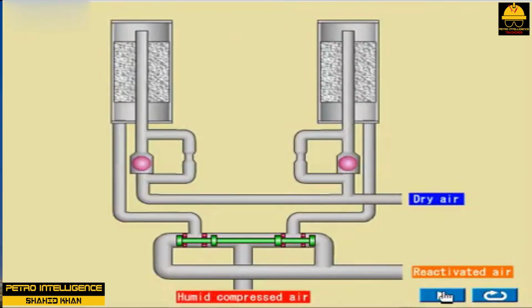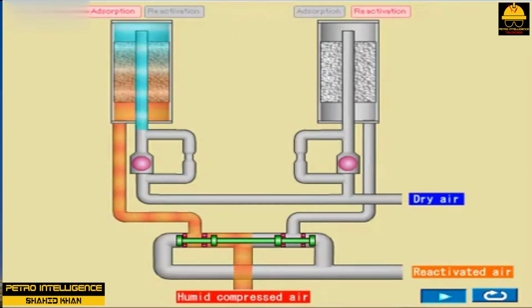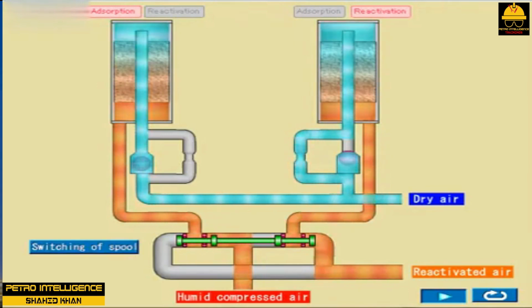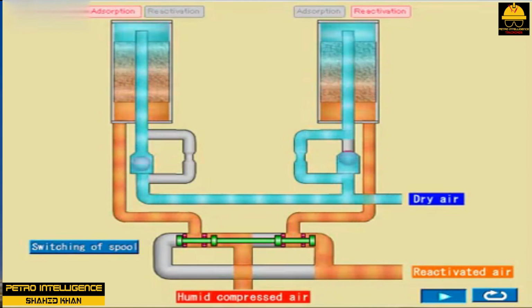A regenerating gas dryer usually consists of two vessels, beds, containing a granular solid. The solid is specifically chosen for its high adsorbency of the target vapor and ease of regeneration. Piping and valves connect these beds such that the gas being dried enters only one bed. The solids in the other bed are separated from the process so that they can be regenerated. When the first bed becomes saturated, it is switched off the line, the second, regenerated bed is put on the line, and the first bed is regenerated.